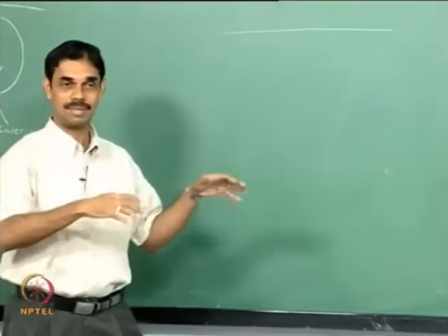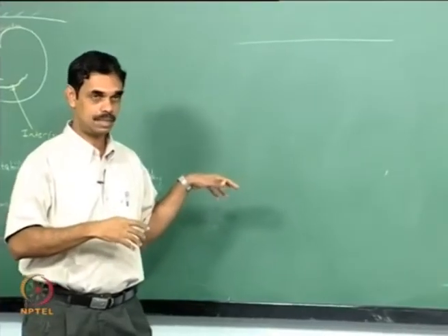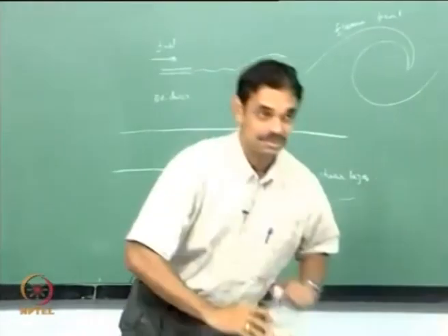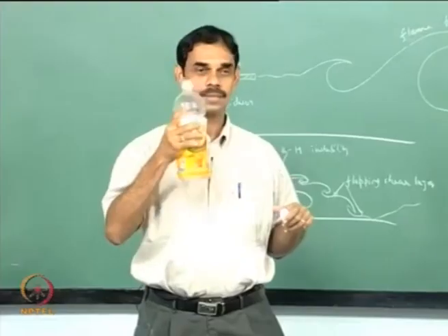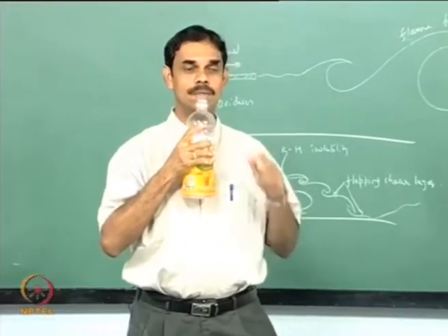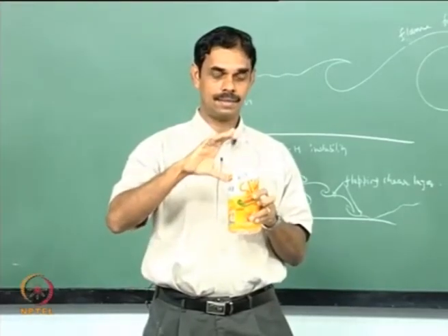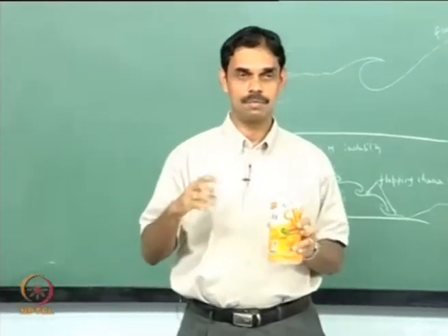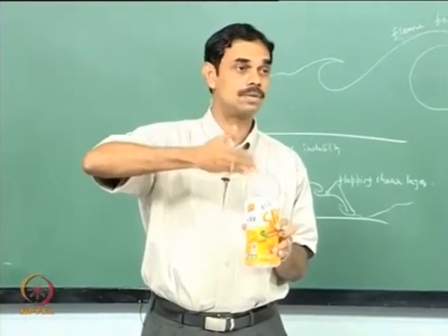So your answer will have to wait a little bit when I speak about aerodynamic generation of sound, and I do not know if this bottle, the water height is right to generate the sound, but let us try. Here there was no combustion, but I am blowing, and I am actually shedding vortices here, and there is a resonator attached. Aerodynamic sound is produced by vortices when the vortex has a trajectory which is perpendicular to the acoustic streamlines.